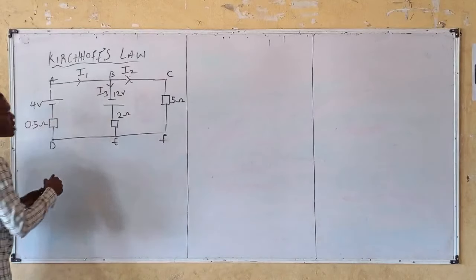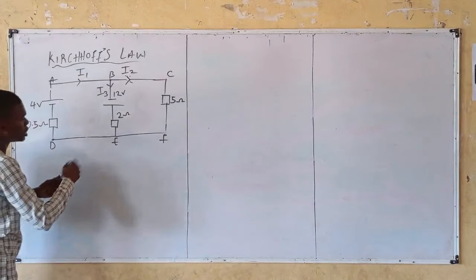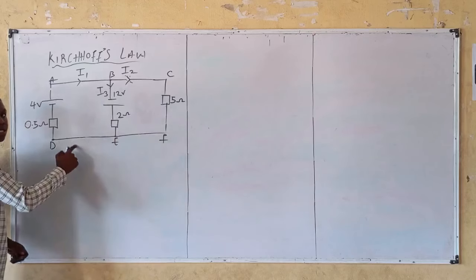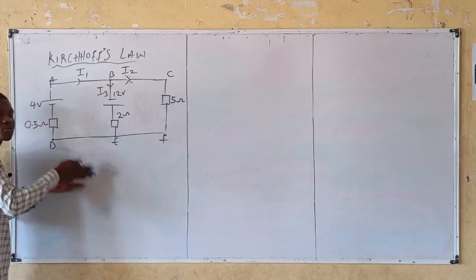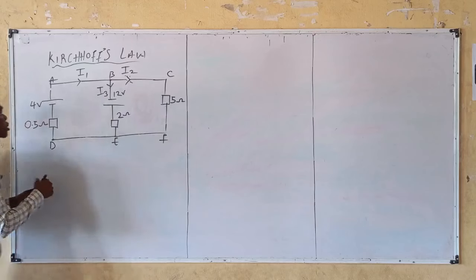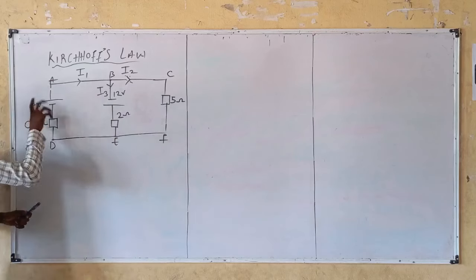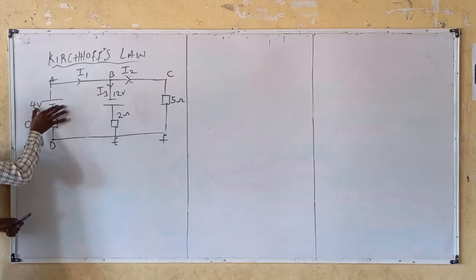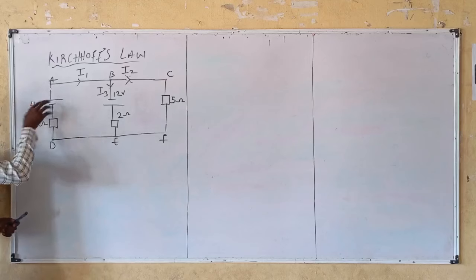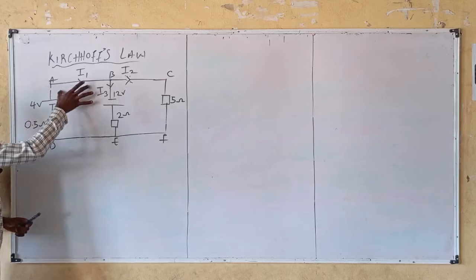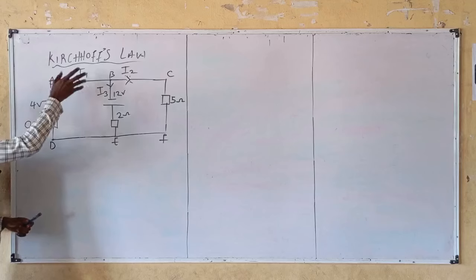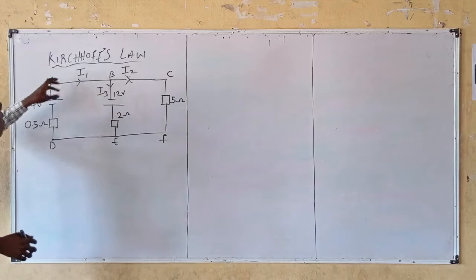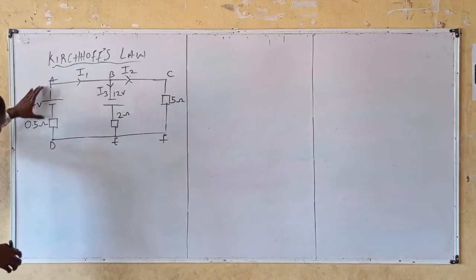This is how it works. This I1, it is simply starting from this E. Let's say I1 is starting from E. There is no circuit element here, so we are not referencing that as a branch. For AD we have circuit elements. We have a resistor and a voltage, meaning we can say this is a branch. Then similarly, we don't have any circuit element here, so we don't reference that as a branch. That's it. Meaning we are saying that the current I1 is for branch AD.